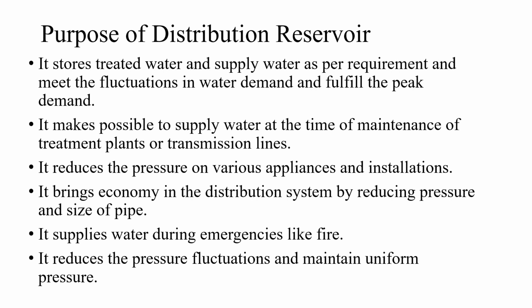Purpose of distribution reservoir, right? It stores treated water and supplies water as required during the peak demand or during the fluctuation in demand as well. It makes it possible to supply water at the time of maintenance of the treatment plant or transmission line, right? During the maintenance work also it can supply water and help distribution. It reduces the pressure on various appliances and installations. It brings economy in the distribution system by reducing pressure and size of the pipe, right? Distribution reservoir helps in reducing pressure and size of the pipe.